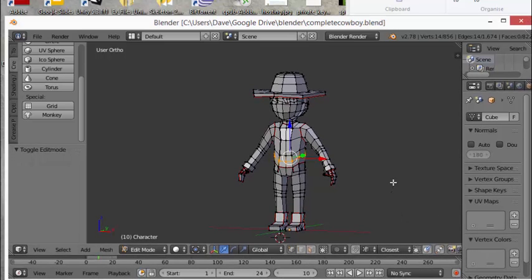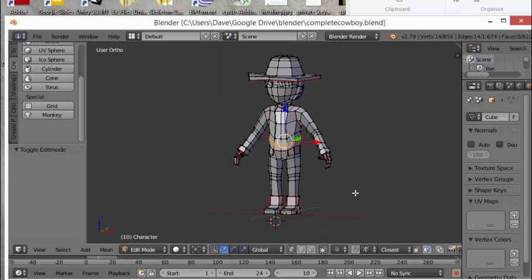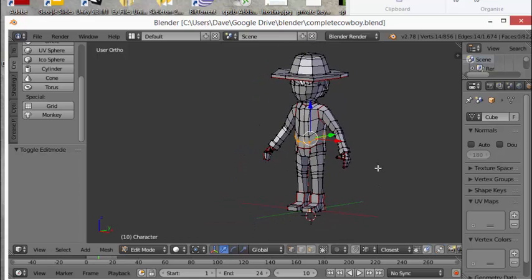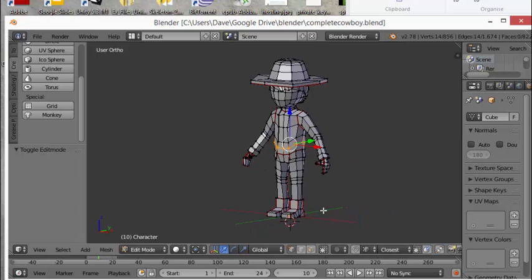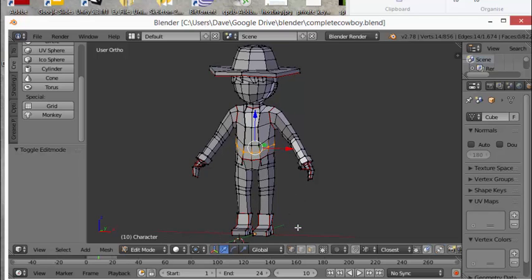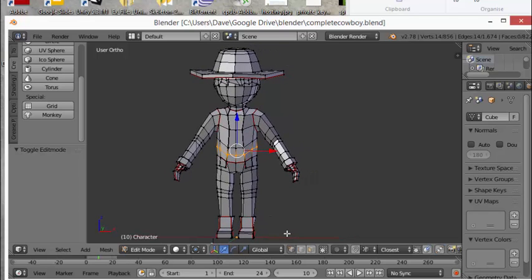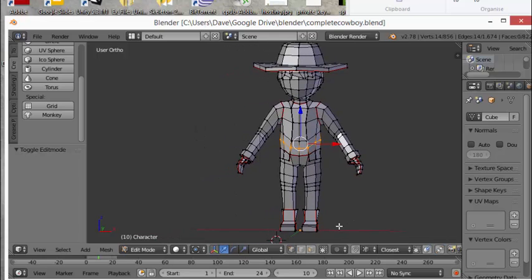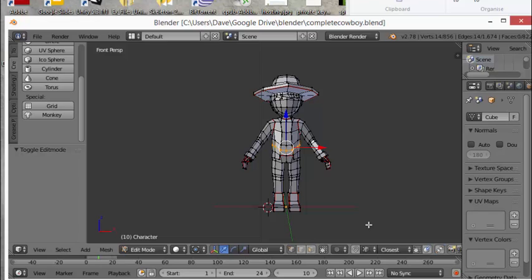And what we're going to do today is use the built-in colours and textures that come with Blender. In this instance mainly just colours and specular highlights to take the boring grey Lambert texture that our Cowboy's got at the moment. You need that when you're modelling, but you don't need it once you've finished modelling.